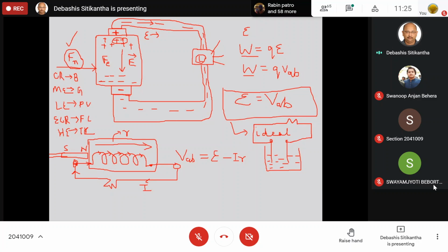Okay, before connecting this load, first I'll measure the voltage across the EMF source, let us say by using a voltmeter. So let us say this voltmeter is giving me a reading of around 13.2 volt. Now if I connect this load to this battery, then you will see that the voltage is now reduced to, let us say, 12.1 volt. So there is a drop of around 1.1 volt.